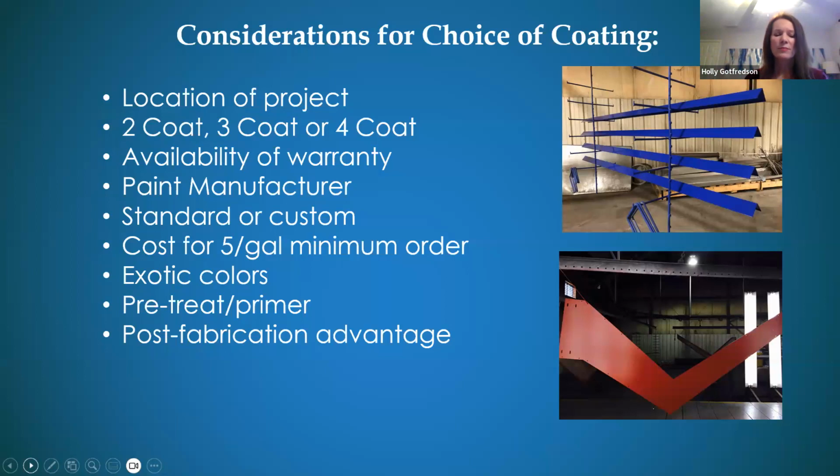So when you're looking at perforated products, something else to consider is the coating. What coating is going to be the correct one for your project? Definitely, we want to know what's the location. Is it going to be something that's on the coast versus something that's in the Midwest, let's say? Those two locations are going to require different things. When you're thinking about the coastline, you're definitely going to want a 3-coat or 4-coat application for that harsh saltwater environment. Also to consider is what's the warranty requirement?